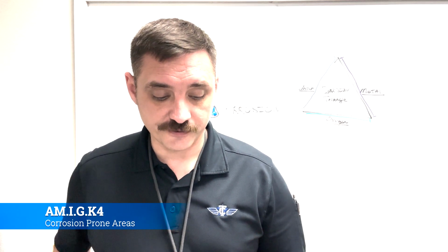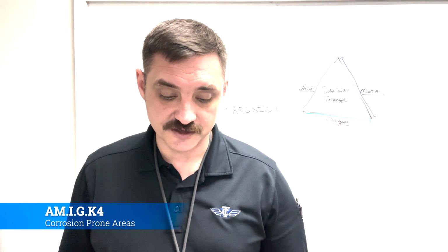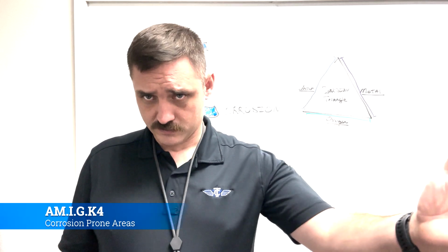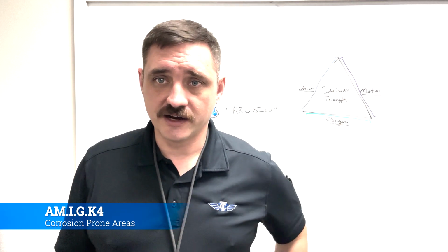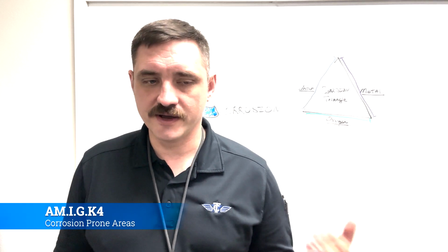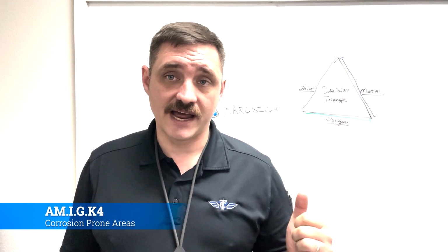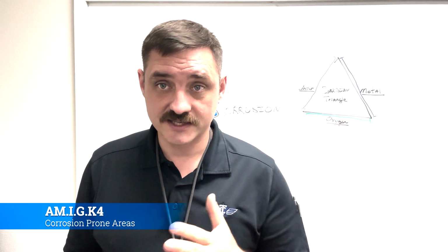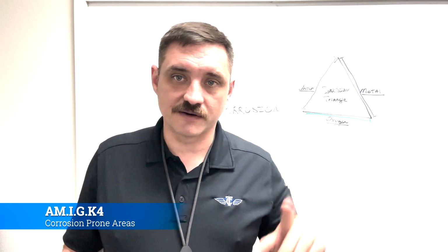Okay, so bilge areas. These are natural collection points for hydraulic fluids, water, dirt, odds and ends of debris. Now, I always tell these stories about taking apart a South China Air 737. When I worked at an MRO, we would strip them down, then sell them to Part 121 carriers in the U.S. Whenever we pulled the blankets out in the bottom, there was always a bunch of junk inside that somebody had dropped, and eventually all things lead to the bottom of the airplane.